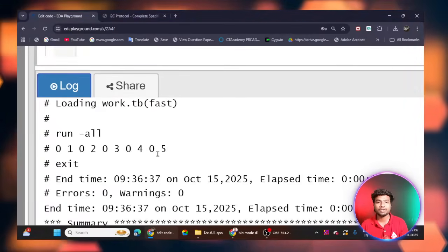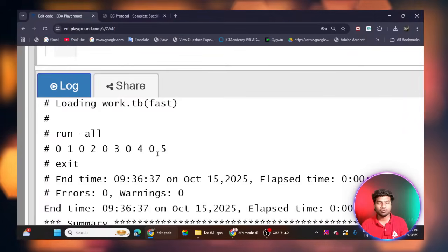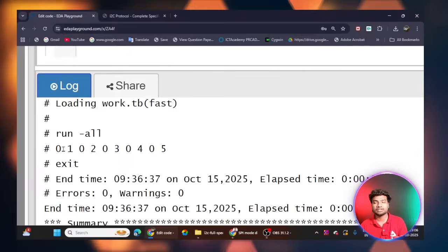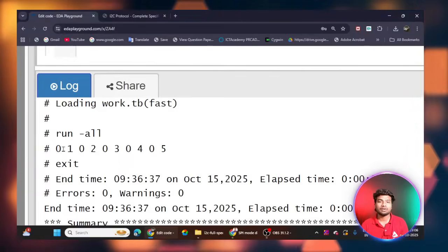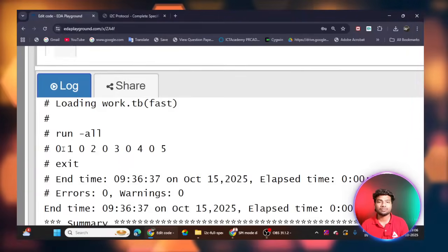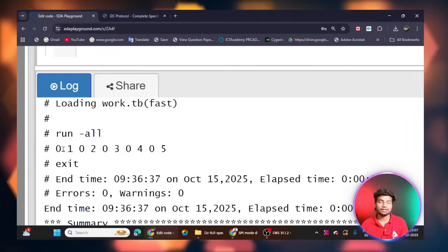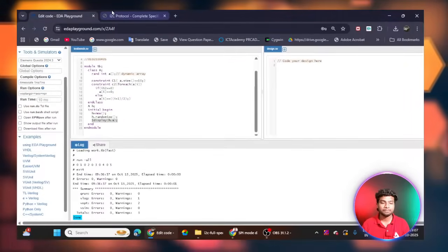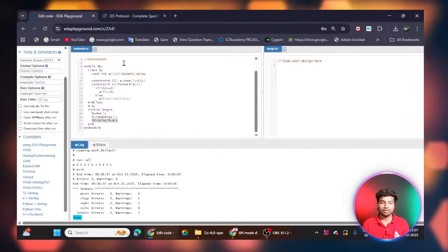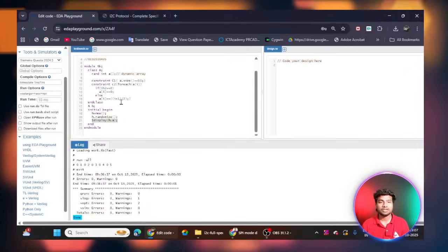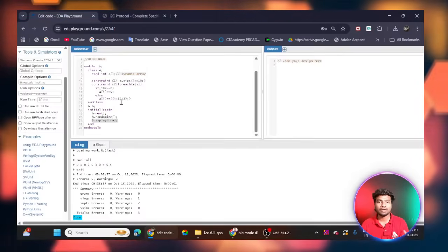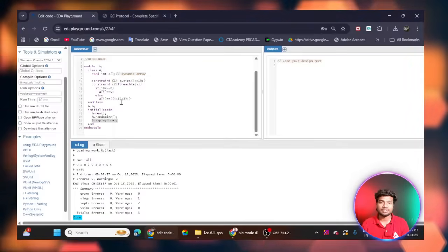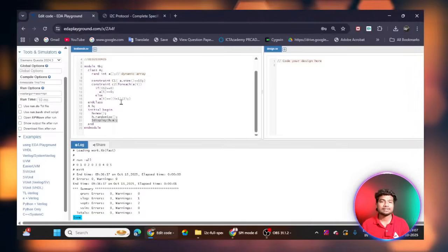And this is how the interviewer will ask the question to make this kind of sequence of outputs. They will ask to print 5 5 5 4 4 4, or like 5 4 5 4 5 4, or any other pattern. So they will ask these kinds of logical questions using the constraint. This is what I'm trying to convey to you: by using the constraint you can limit the randomization, and you can also do your logic using the constraint while writing SystemVerilog code.